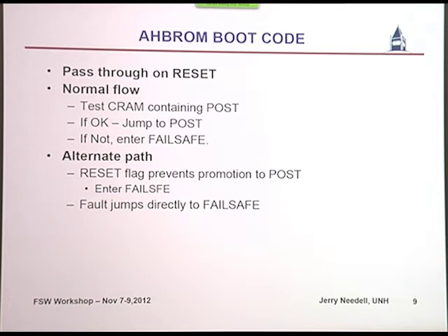The general philosophy of this boot code is, as the keynote speaker was talking about, you spend a lot of time developing this code that you hope you never use. The main job of the AHBROM code is to get through it and get on to the higher level code, pass things on to the power on self-test that's in the CRAM, which then passes code on to the RTEMS image that is also running out of the CRAM. So in the best case, you spend very little time in this code and never use any of it.